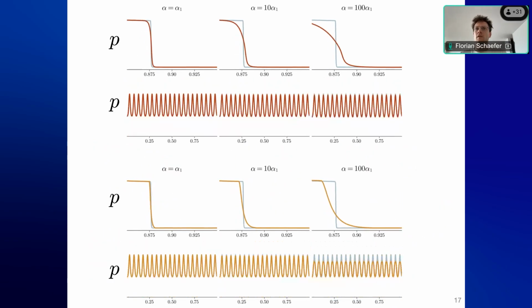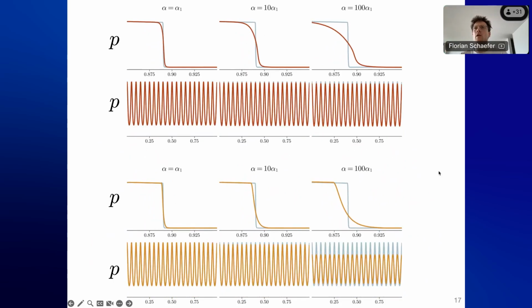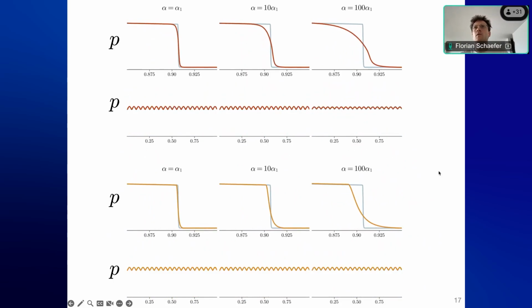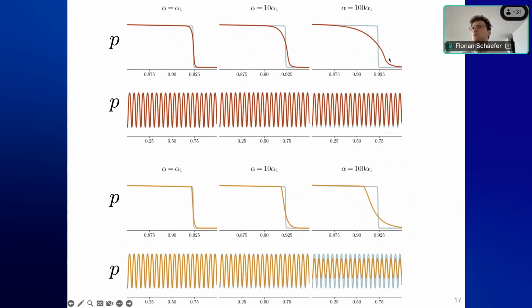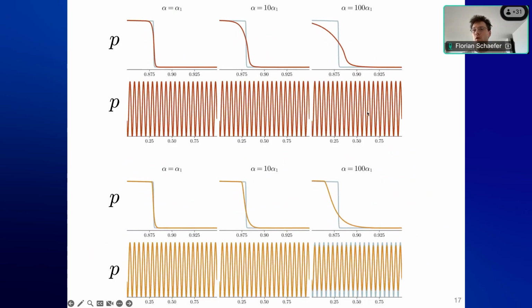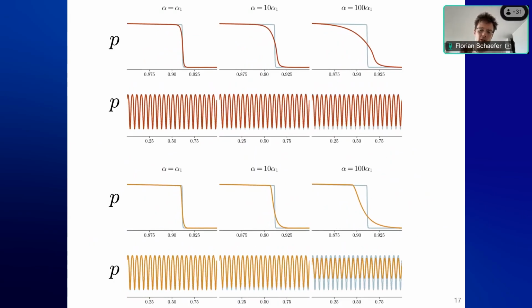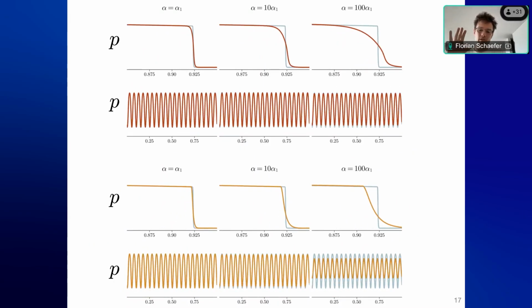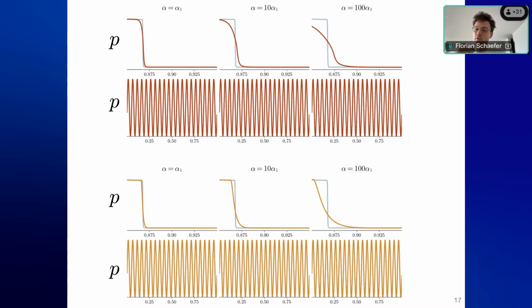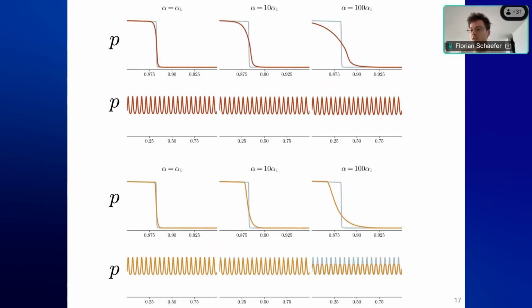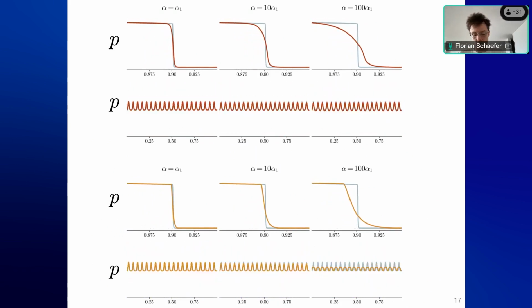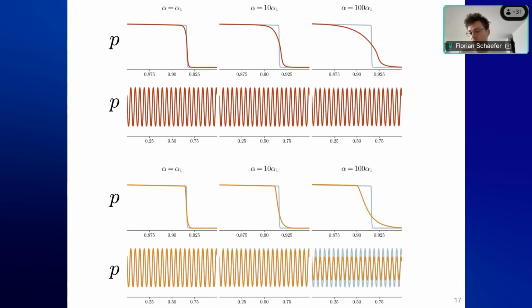If we compare again against this localized artificial diffusivity approach, we see that it has generally smooth profiles, high order smooth profiles, with next to no dissipation in these oscillations. So something that's very good about this is distinguishing shocks that are replaced with smooth profiles that we can then easily resolve with higher order numerical methods without affecting oscillatory structures.